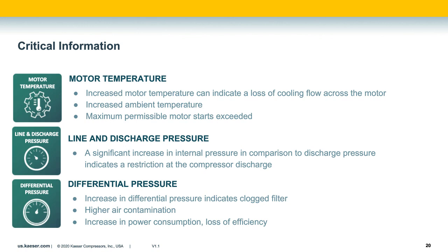or something like that. Increased differential pressure for your oil is also something to be cognizant of, as well as for inlet filters. So it's a good gauge of whether there are clogged or contaminated filters, and furthermore, whether a permanent replacement is needed due to higher ambient contamination. So those are things that you want to be looking at.